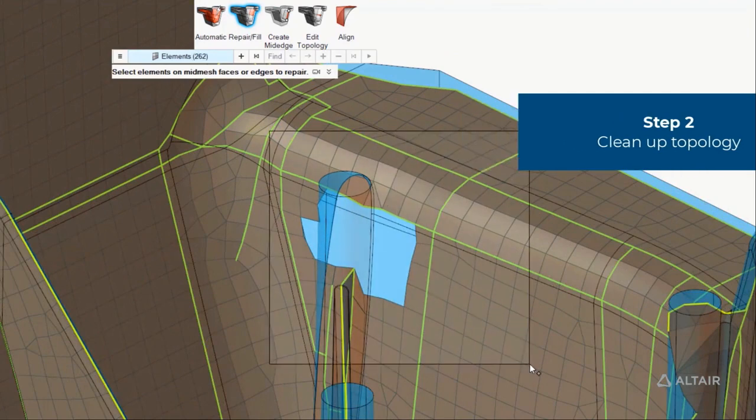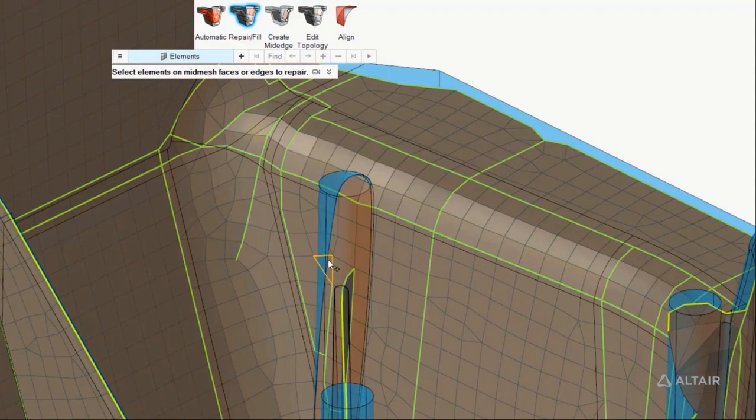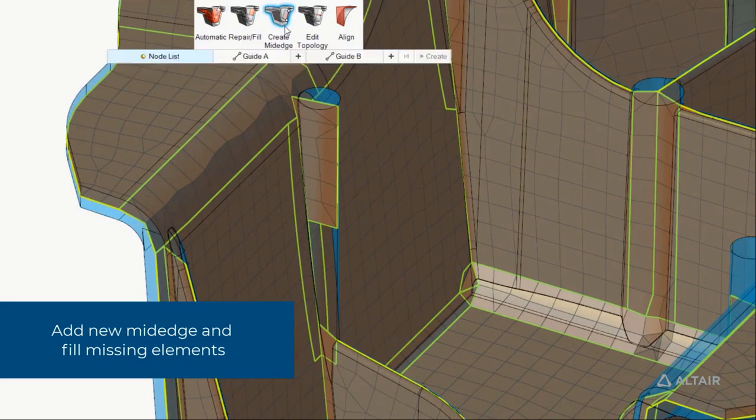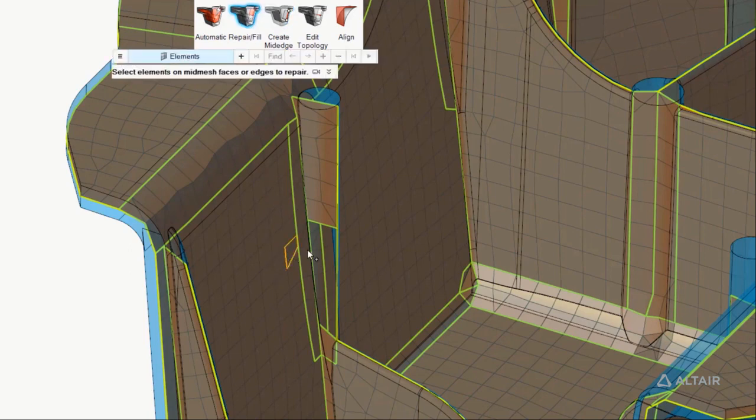From here, these tools operate on the mesh representation of the midplane, not a geometric one. So editing faces, filling in faces, or removing features from geometry onto the underlying mesh will now dictate how the batch mesher handles them when we perform a rebuild in the end.